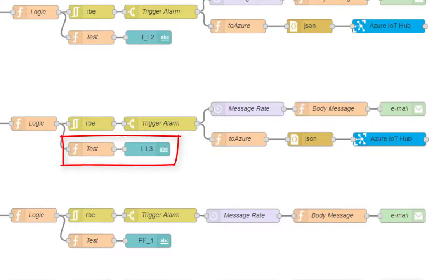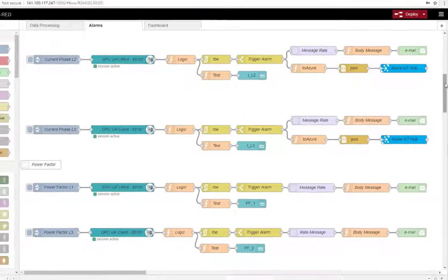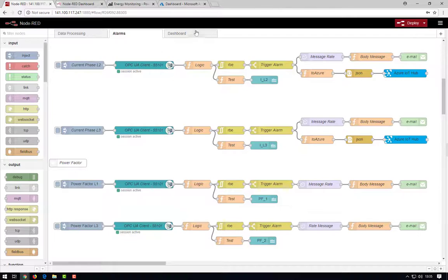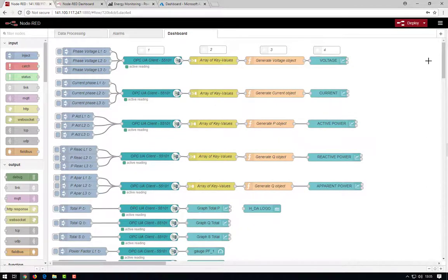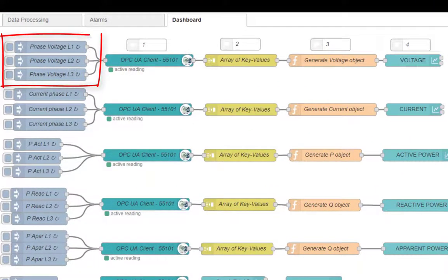These 2 blocks configure an LED in the Node-RED dashboard, which will be the next flow introduced, to show graphically the alarms. A SCADA containing the energy data is created thanks to the Node-RED dashboard node. In this case the data are collected by variables to create a single graph with the values of each line.